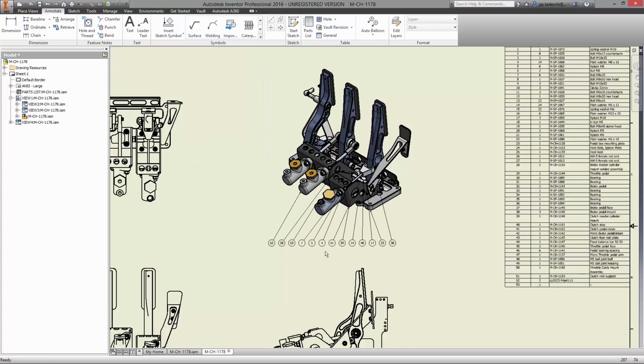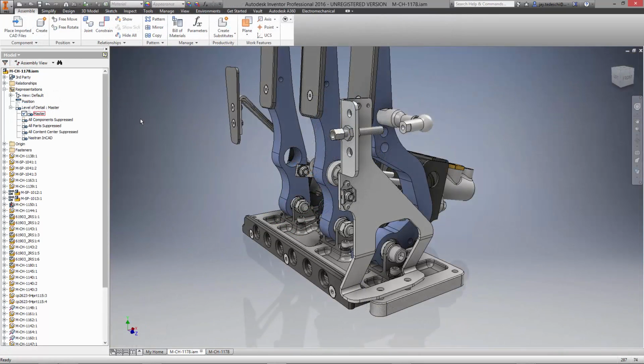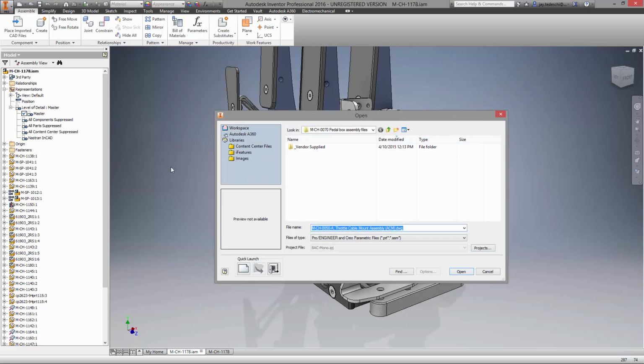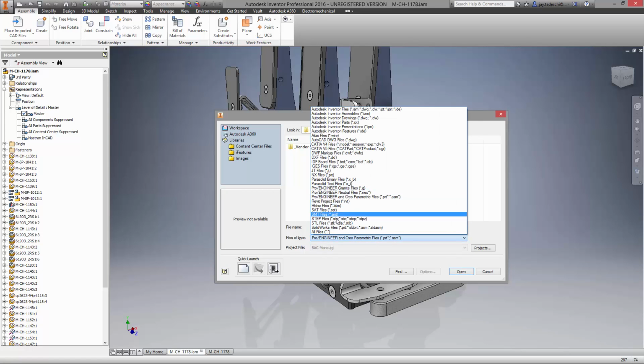They can be aligned in any direction, even use existing entities to align them to the orientation of the components in the view. Let's talk about sheet metal. We have a new design for the throttle mount on the far right that is designed as two pieces of sheet metal welded together. Inventor 2016 provides the ability to design the two sheet metal components as a multi-body part. This is a big time saver as opposed to working with the two components in the assembly environment.